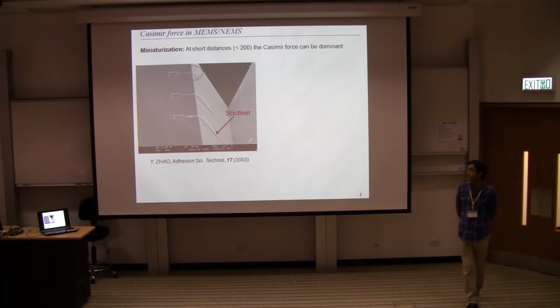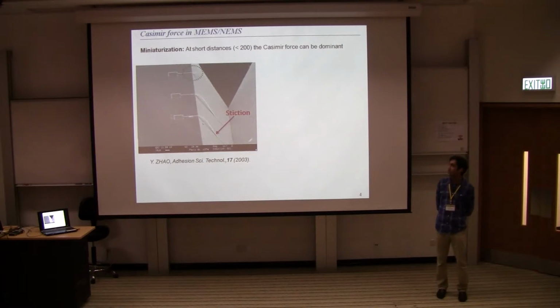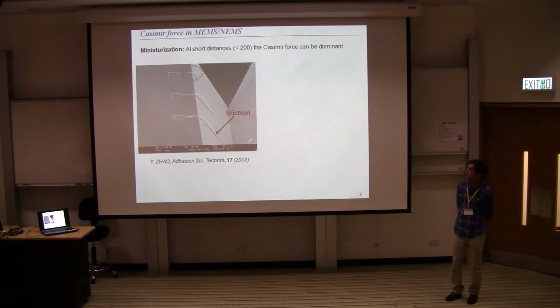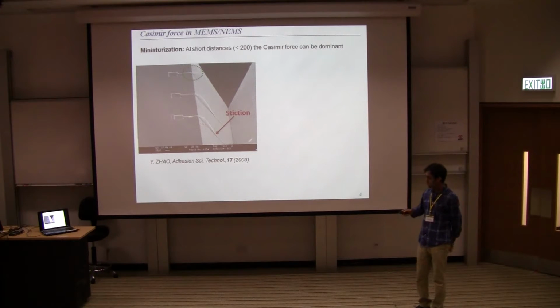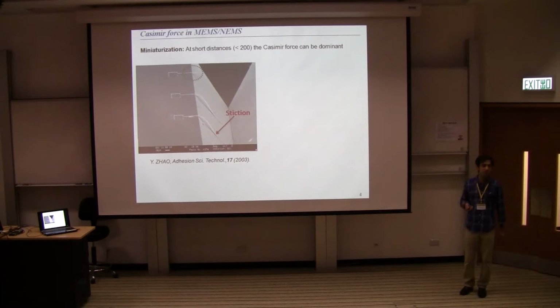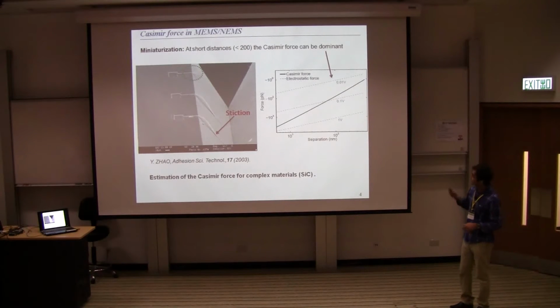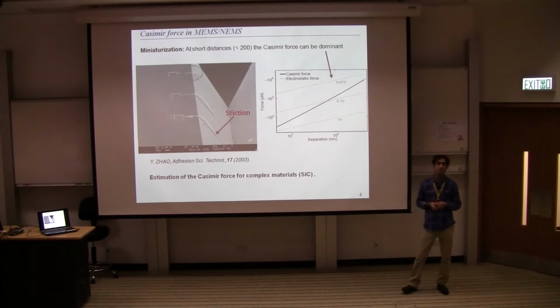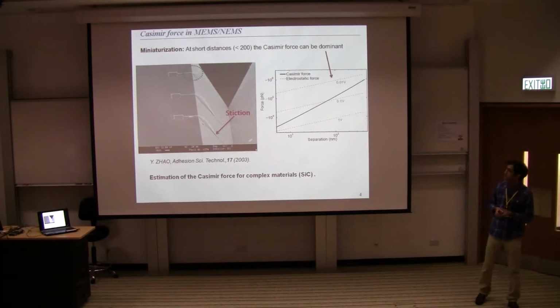microelectromechanical systems have the right size for the Casimir force to exert, because they have a big area and a small gap, which can pull components together and lock them permanently, which we know as a malfunction called stiction. By miniaturization toward nano-electromechanical systems, the distance between the elements has become shorter, so therefore the forces become more dominant.